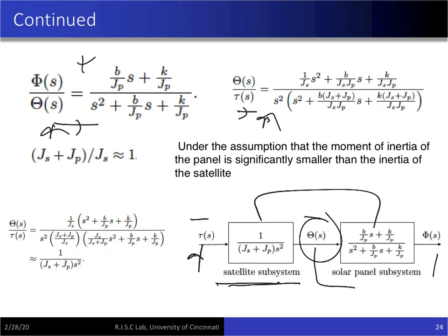Okay? So that's one important piece of intuition here, that you can break down transfer functions, and you will see this is very important when you are designing controllers for complicated systems. You can first solve for theta s to give you a phi s, and then you can solve for that theta s, for which you will need torque.